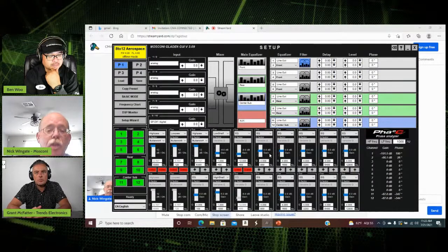Every time you go up in value, you are narrowing the amount of information we are affecting either side of 400 hertz. In this particular instance, I went from a Q of 4 to a Q of 12, which narrows the information significantly. And when we've done that, we've noticed on the RTA that 315 and 500 went back to normal, to where we were looking at it before we started playing with this.